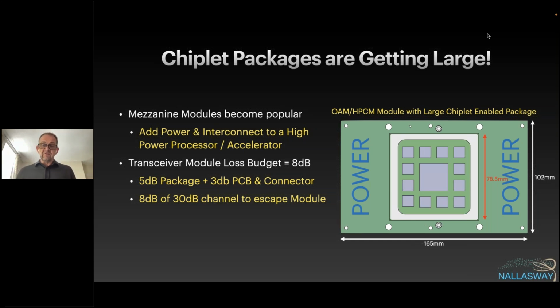And then you've got about 14 dB left to traverse those modules. Now, for those of you that know OAM, this is where it really hit me across the face. The universal baseboard that the OAM modules sit on has a liberal spreading of retimers just to get across the backplane to the PCI switches, or even to get into the QSFP-DD modules for fabric expansion.